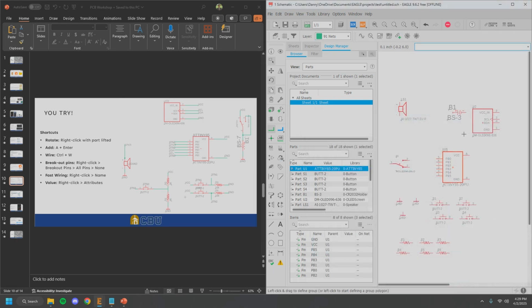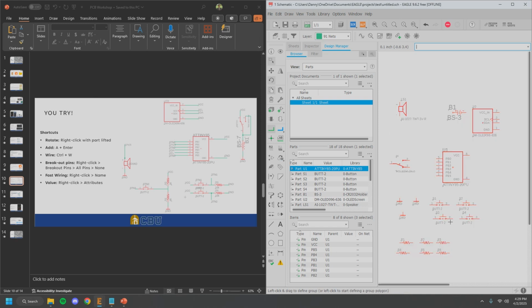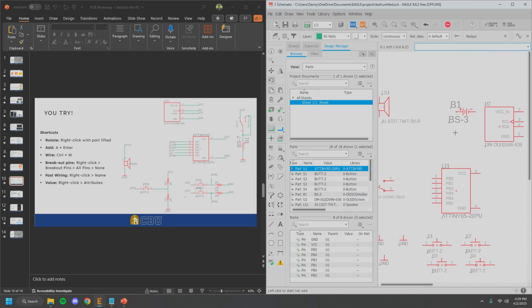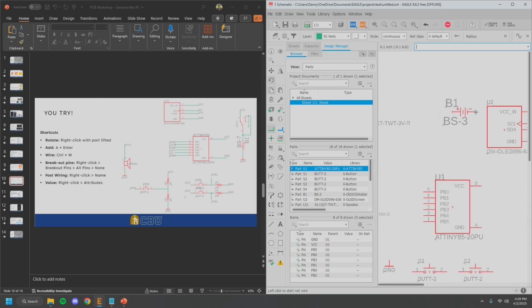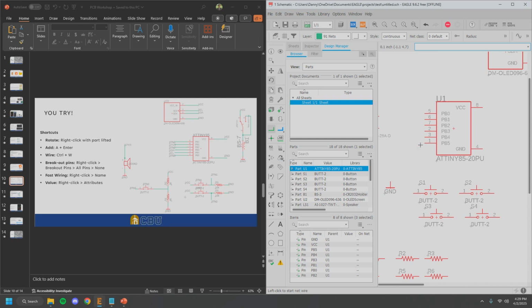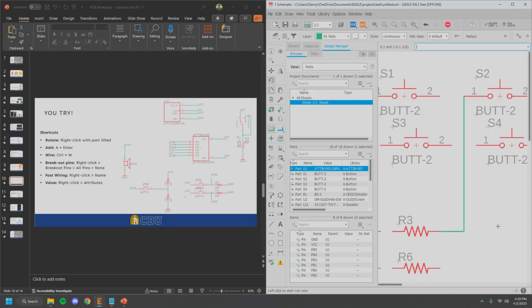So after you populate all the components on the board, this is declaring to Eagle, these are all the components that our board is going to be using. It now recognizes all these and it's just waiting for us to wire them up. So the way you're going to want to explain it to students how to wire it up is that's what our net button is for. Again, you were just clicking on add part. The second most important one is net. So what net does, if you click on it, you can see it'll make a little circle around every single one of these pins that we have for each component. And if you were to click on one, it's allowing you to say, hey, these two are connected.